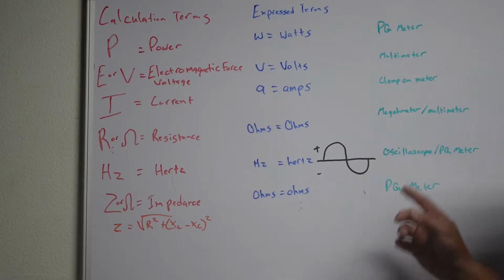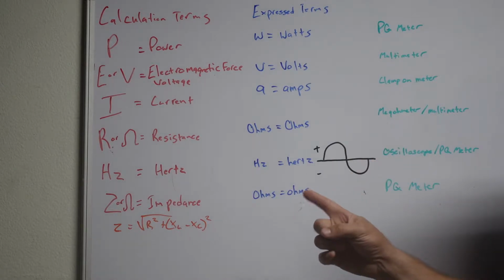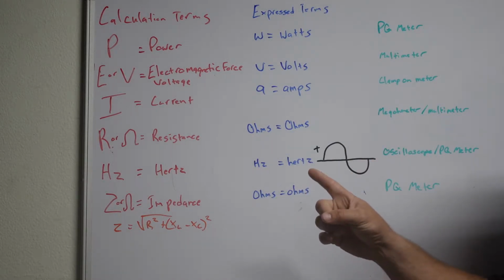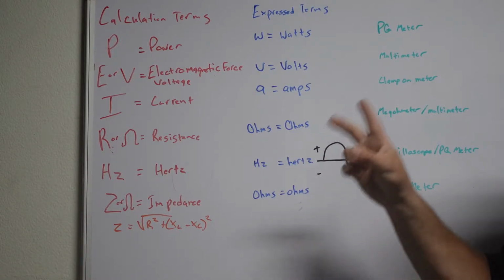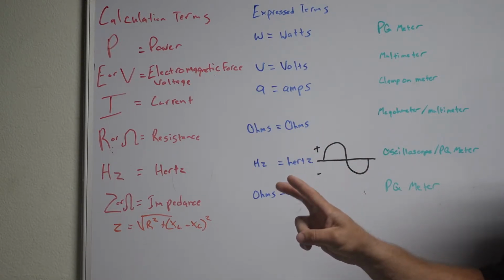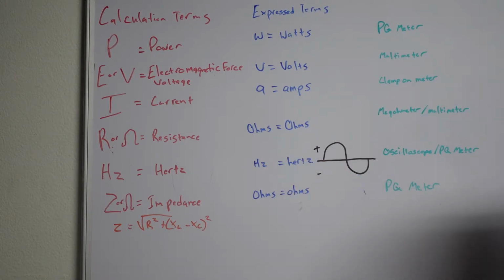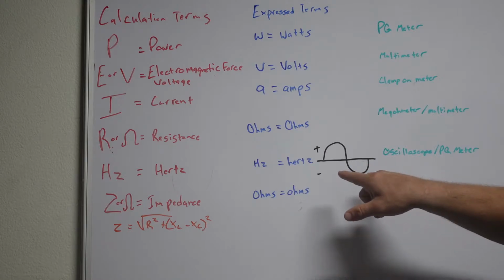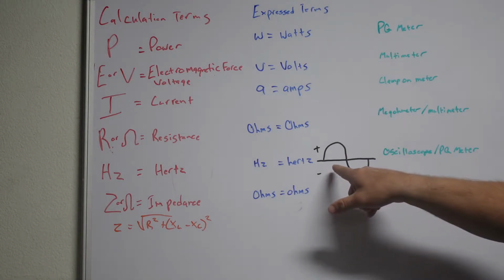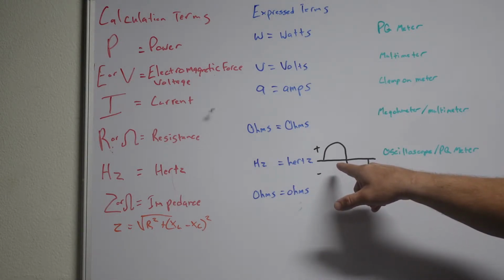So for 1 minute, if you were to time 60 seconds, which is how many seconds are in a minute, times how many revolutions per second, which would be 60, it would be 3,600. That's important for synchronous motors, but just an idea of how fast that generator is actually spinning to get to that.